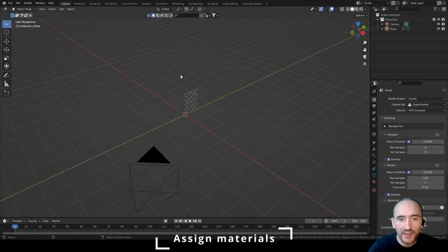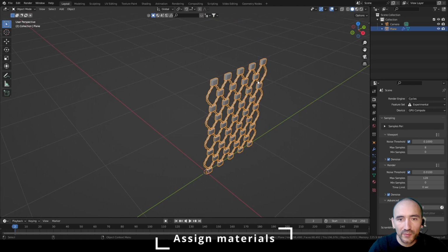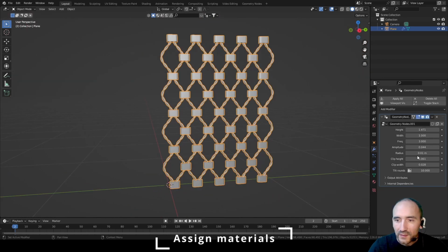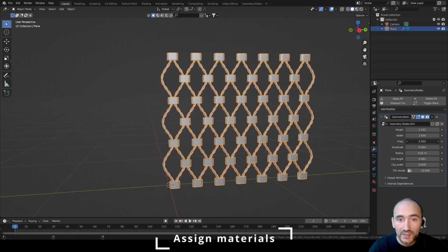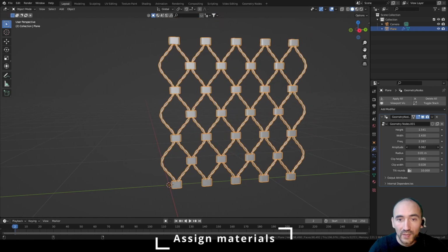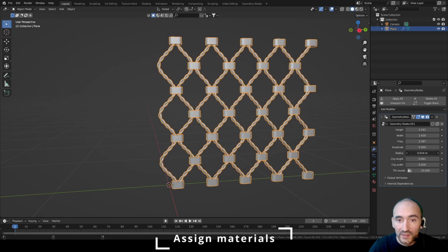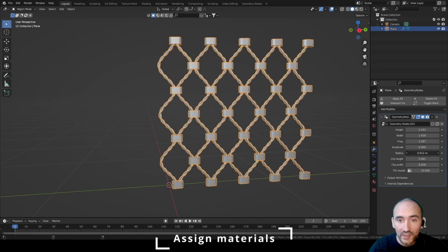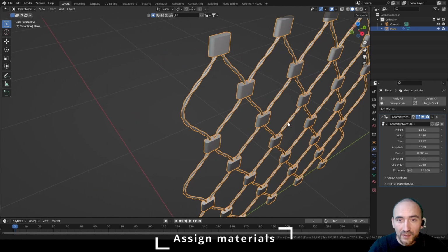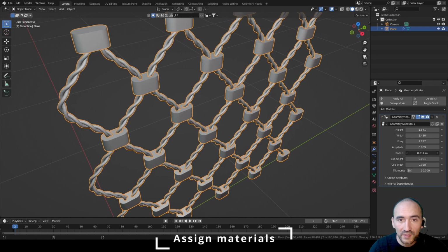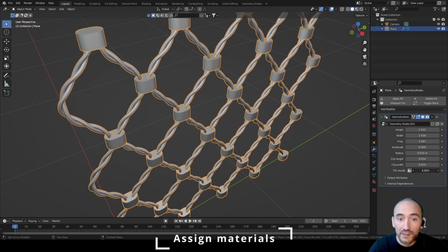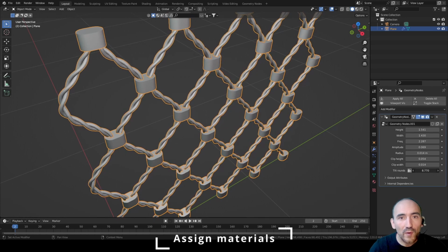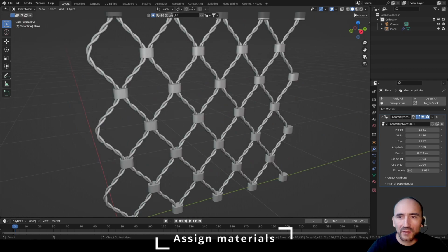Now if I go in the layout viewport, select the geometry, focus on it, we can play with the height, we can increase or decrease the frequency that we want on our geometry, we can increase the amplitude, we can increase the radius of our geometry, and you can see the clip changes in relationship with this radius. We can control the height and the width of this clip, and we can increase or decrease the tilt attribute of our wires. Let's create a better material for the clipping.